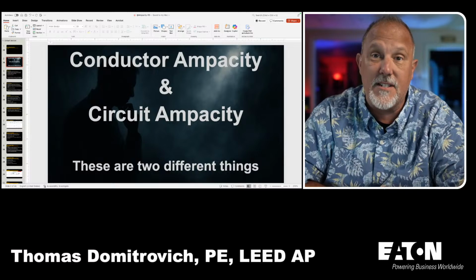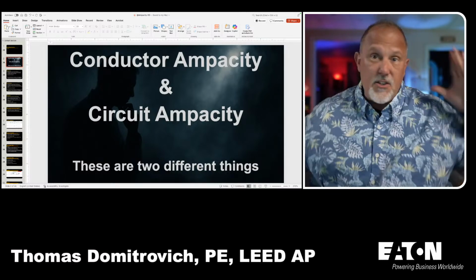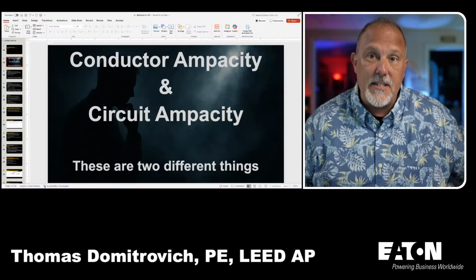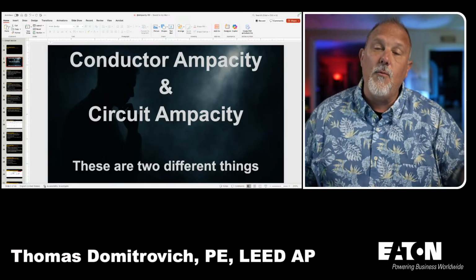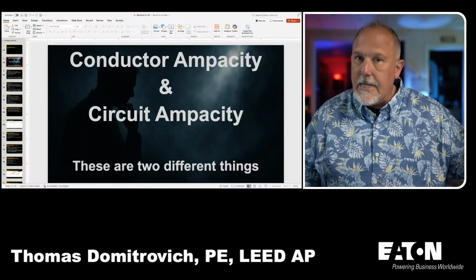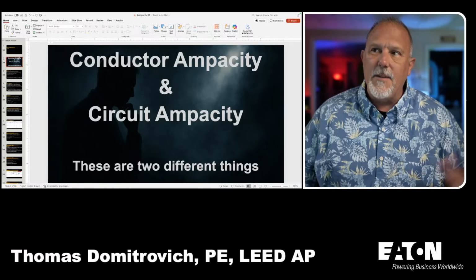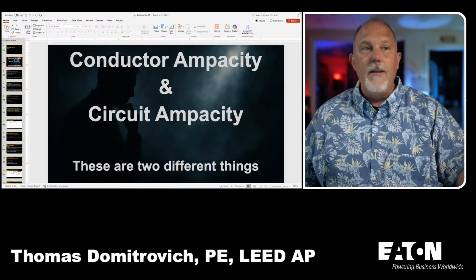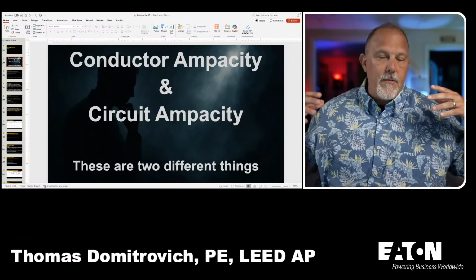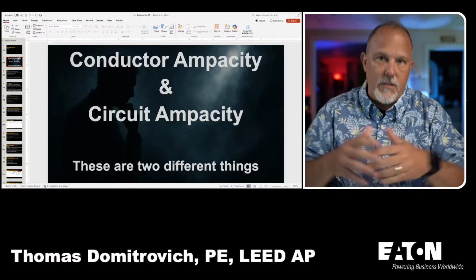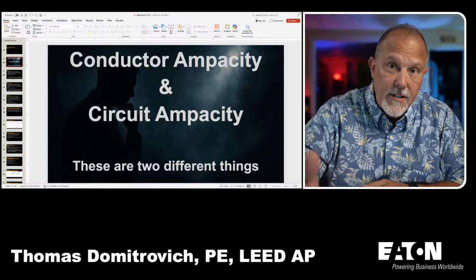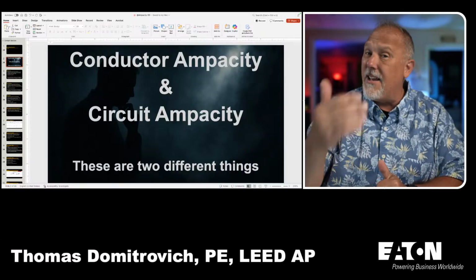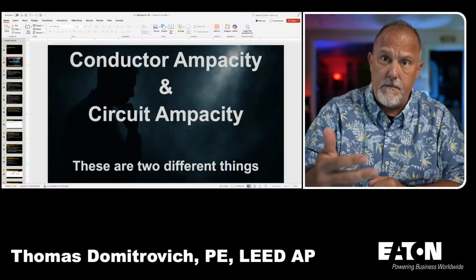Hey, Steve, I'm continuing this discussion from yesterday. All of this started from a customer asking a basic question, and I gave him an answer, and I know the answer was right, and he's satisfied. But then I looked at what I said, and I'm like, wait a second, where is that supported in the code? I really couldn't find it. So I started to do a deep dive on conductor ampacity, and I've come to the conclusion that I have conductor ampacity and circuit ampacity, and they are two different things.